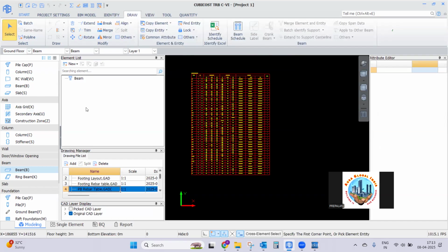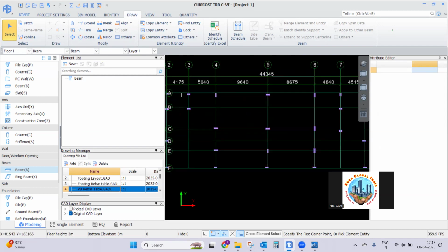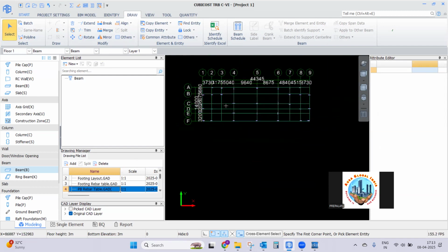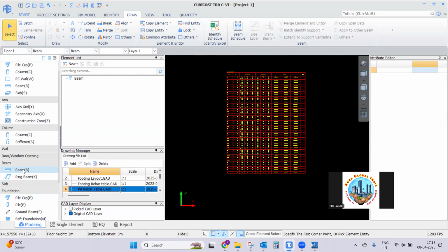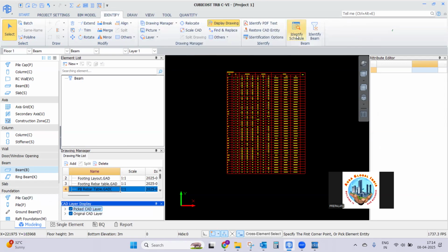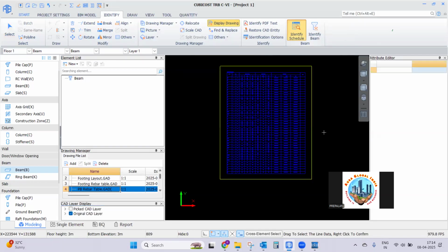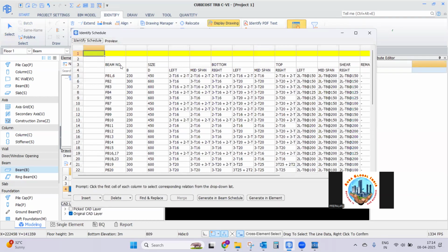So to read the beams, better I will do it here. First we need to read the beam table. So select the beam schedule, drag window the beam table, and then set the headings.